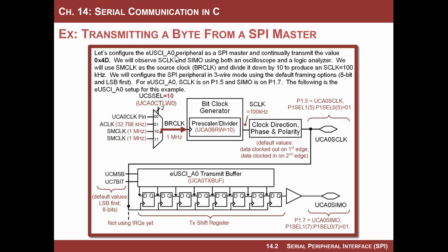So we've looked at the UART, and we were using the A1 peripheral because that was the application UART that we could send information up to the terminal. This time, let's use the A0 peripheral, which happens to come out to other pins on the LaunchPad board. But this is the task ahead of us, okay?